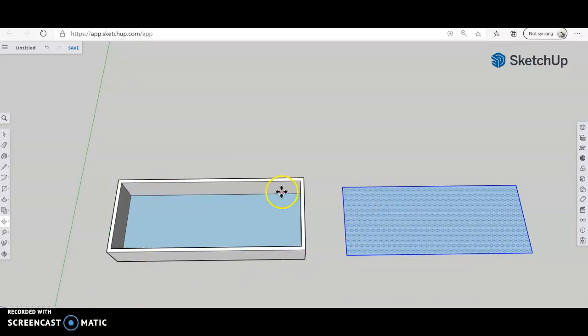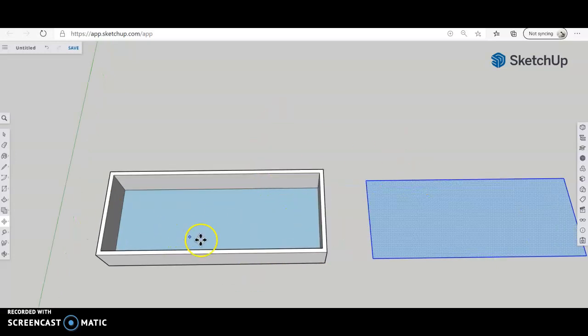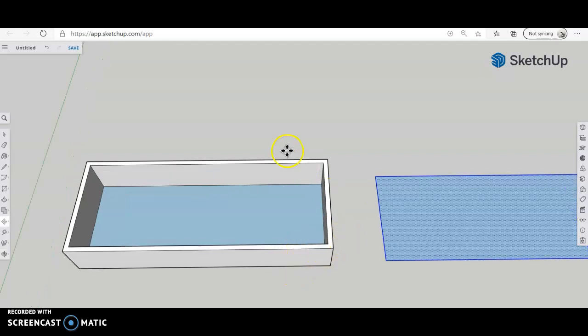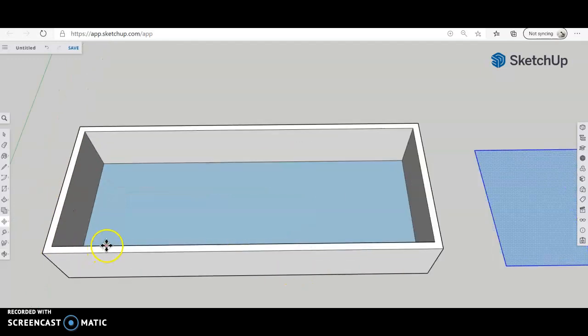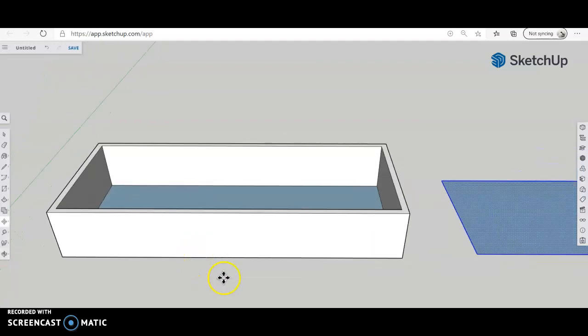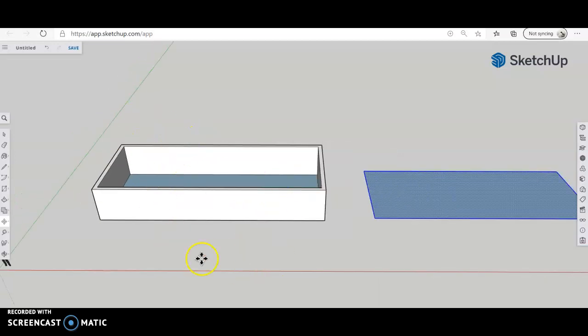But you're going to use whatever size that you plan on doing. So what I did was I created a 50 feet by 20 feet rectangle, and then I created my outside walls, which are 11 inches in thickness. Okay, and then I raised that 8 feet because a typical wall is 8 feet in a house. And so that's why I have this looking like this. I didn't put anything inside just for the sake of showing you how to create a roof.